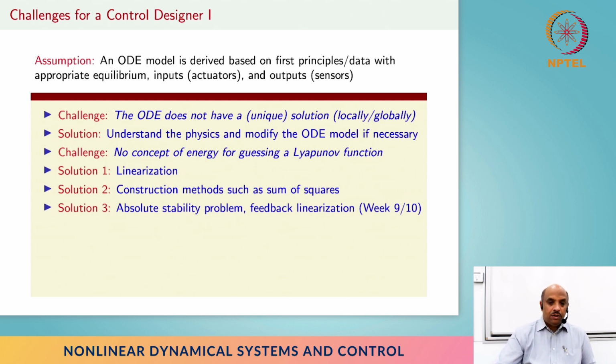Another way of doing it is, okay, maybe take this nonlinear problem, divide into some linear part and then nonlinear part, or both nonlinear, and then the nonlinear part is much more well behaved, as we have seen. Somehow perhaps it has a dissipativity property, and then we can think of it as a feedback interconnection of two dissipative systems, and that's what absolute stability and robust stability problems do, right? Robust stability is typically discussed in the case of linear systems, whereas absolute stability is its extension to nonlinear systems, right?